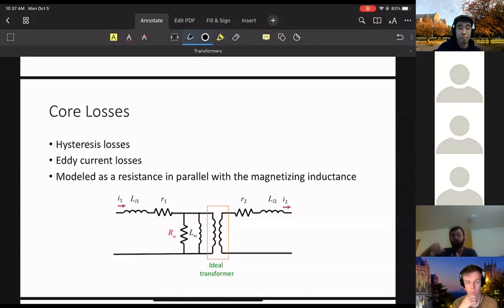But again, this doesn't mean the primary side is special in any way. This is just saying that, for circuit analysis reasons, we draw this on the primary side. These two elements model the entire core of the transformer. So this is the circuit model we have. Any other questions? In the next homework, you'll be seeing this kind of model quite a bit.